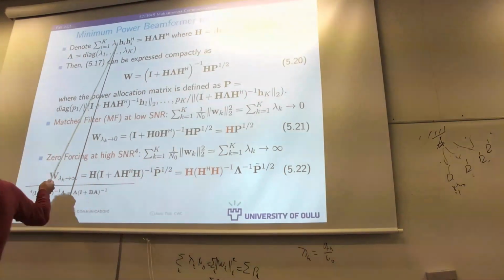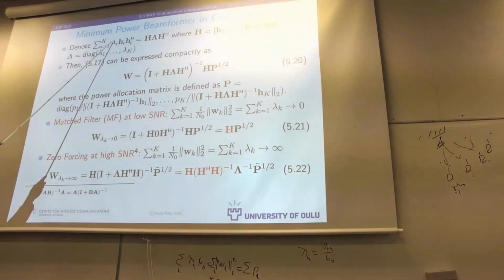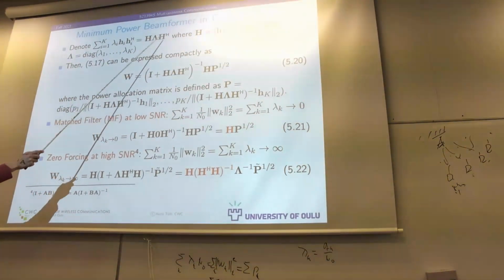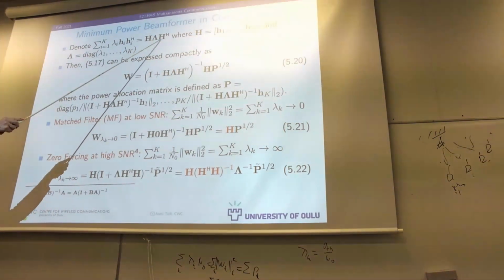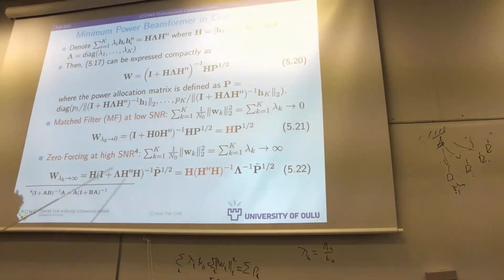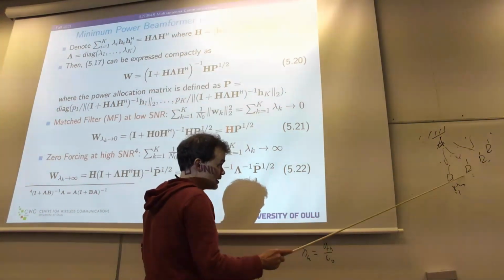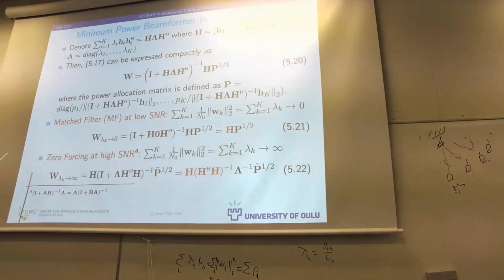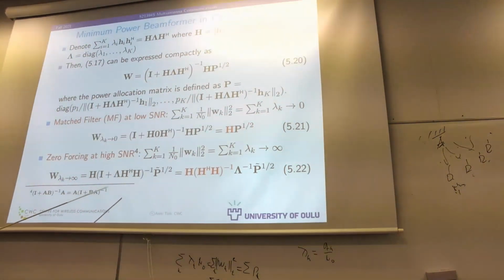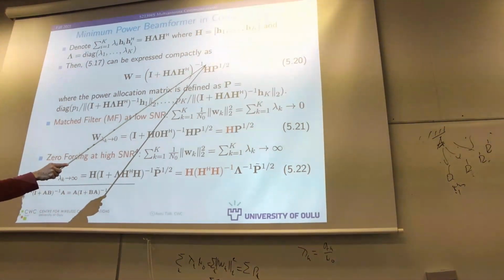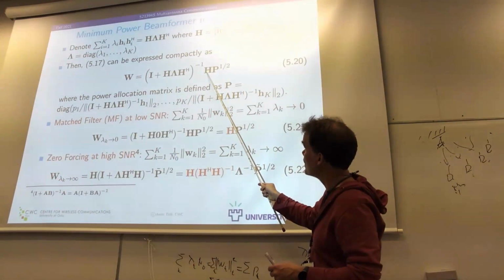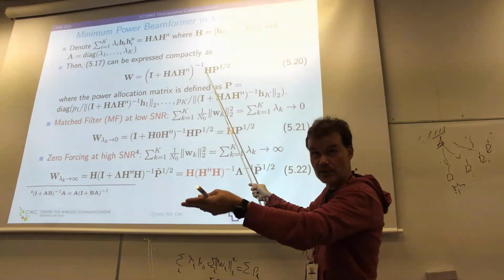Now we have these optimum lambdas from the fixed point iteration. We can write it as a diagonal of lambdas. So this summation here, we can write in a matrix form, H diagonal lambda matrix H Hermitian, where H is just a stacked matrix of user-specific channel vectors. You just stack these capital K channels into one matrix. So now the inverse is just replacing this term with the matrix multiplication. And recall that the user-specific beamformer depends on the matched filter matched to that particular user k, right?